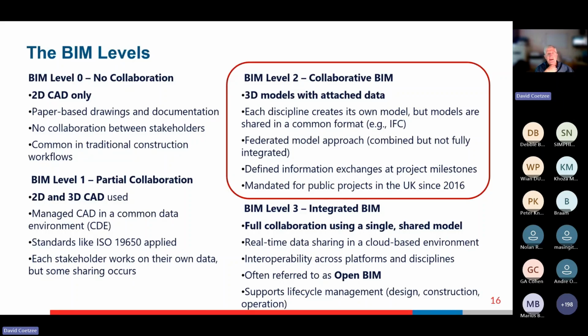There are many others out there, and different people have different preferences. Then one of my team will federate that model, and what that means is he adds them all together and makes sure that we're using the same coordinate referencing space. And then one of the most important things we do is we use the federated model to do clash detection.